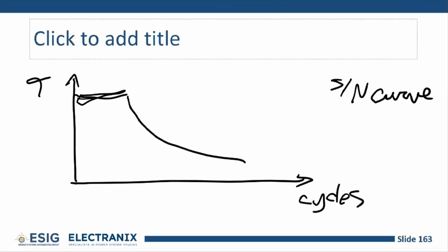Okay, so what we're thinking about is for a generator shaft, this is long, well known. If you put a fault on the system, you get a very big spike in torque on the generator shaft components. Each of these is designed to handle a number of faults in their lifetime.